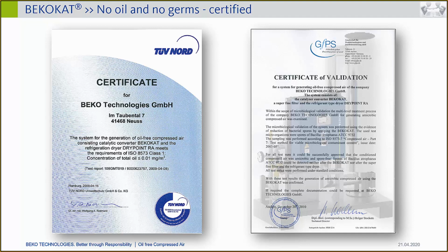I think I heard about that scenario, that there was one measurement done after the dryer, but I wasn't sure if that was a lubricated or oil-free compressor. I have no correct answer on that. What I can only explain is that somehow the oil vapor is also being adsorbed within the desiccant. If that works long term, it's something I cannot promise and I cannot explain, but it definitely occurs. But I would not rely on such a system only with the